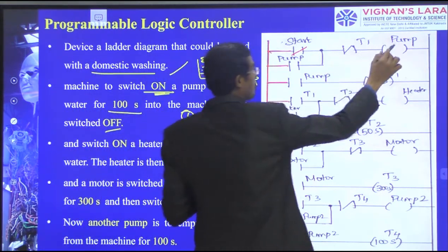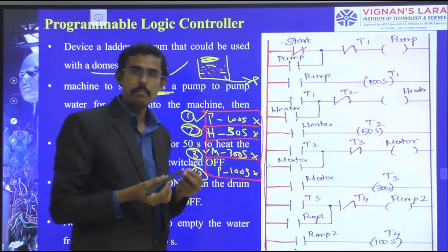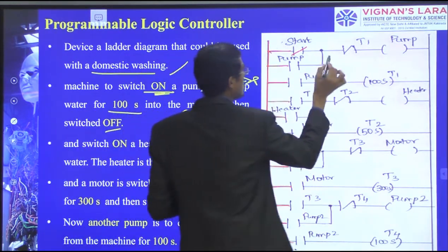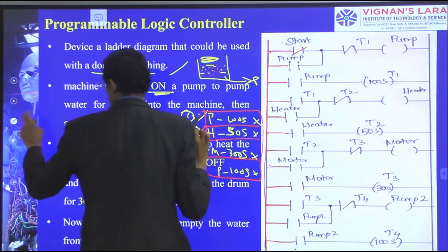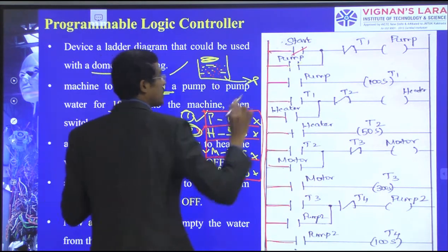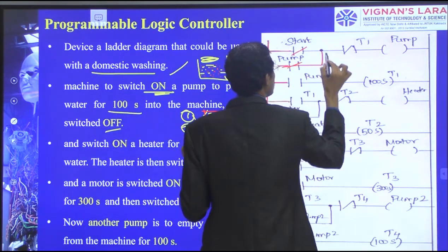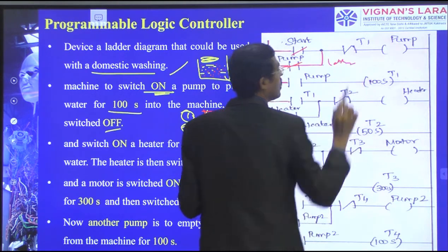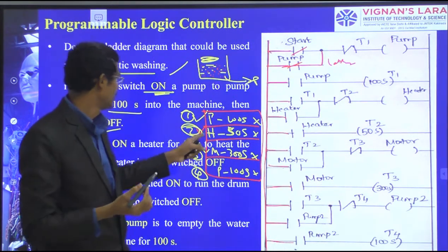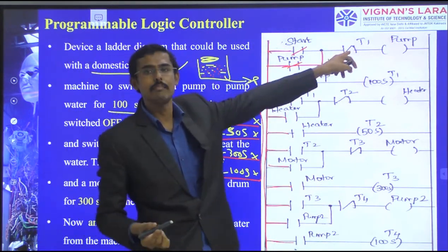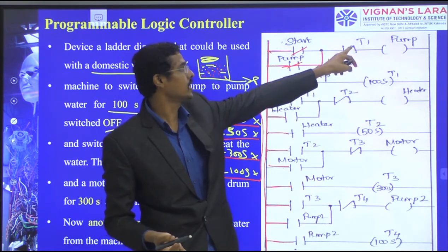So first I on the pump. The pump may run continuously. Therefore I have done the latching process also. Latching is done, up to timer of 100 seconds. That is why I have made the break contact there. After 100 seconds it will break the pump.